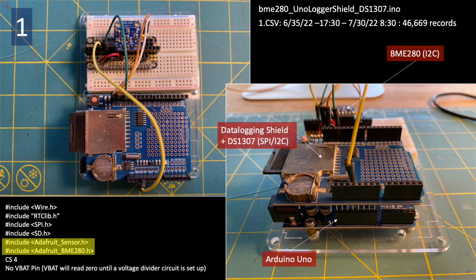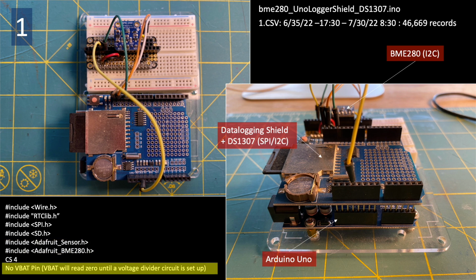Needless to say, we'll need to include reference to libraries for our sensors. In this case, this is what's suggested by Adafruit for use with its BME280 breakout board for measuring temperature, humidity, and pressure. And finally, all the sketches I'm sharing include reference to a VBAT pin, which, when attached to a voltage divider circuit, can help us read battery voltage for remotely deployed units. Adafruit is kind enough to include a voltage divider on its Feather boards, but in the case of the Arduino Uno, I leave this undefined.